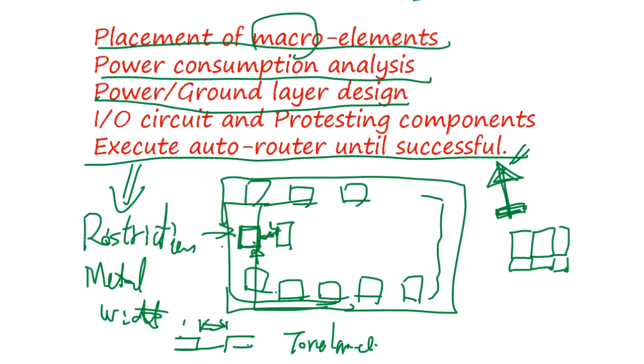Okay. So after all of this is done, finally the chip is processed and created, and when the chip is made, the functionality is verified by defect test patterns. If it all passes, then hopefully this LSI chip is usable. Okay, so that's a quick rundown of the entire process of designing one LSI chip. If it's not an LSI chip, say linear, the design is a little bit different, and a high-speed communication chip will be a little bit different. Each IC chip has different requirements for testing and process, but overall these are the software tools and the process methodology used.